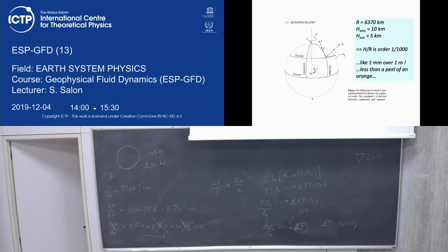Okay. Good. So we started from the conservation of mass and we obtained the conservation of volume. This says that if your divergence is 0, the flows are always divergence free. This means that you have incompressibility of the flows. Another important implication is that you don't have any sound waves, because sound waves are due to change in density.